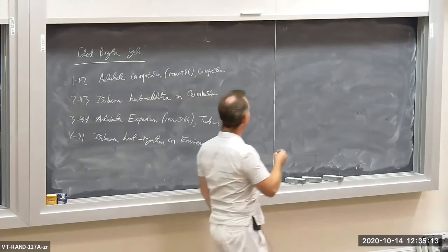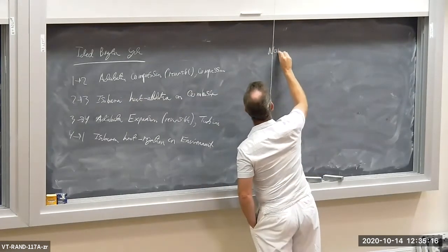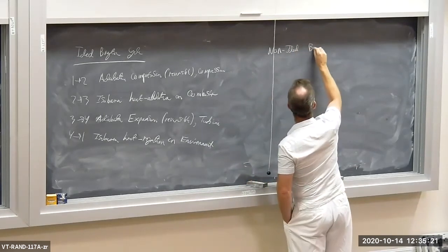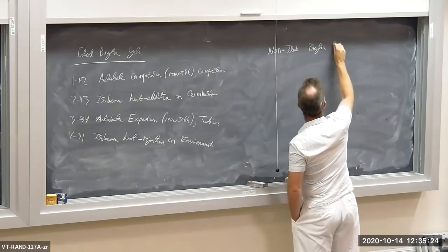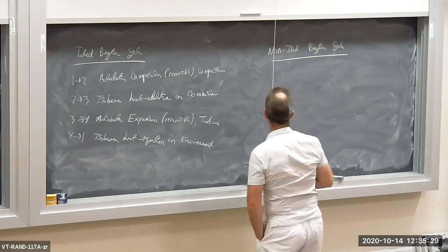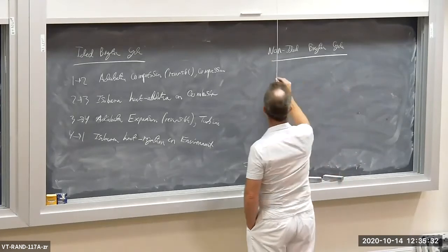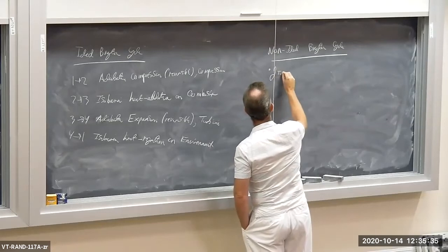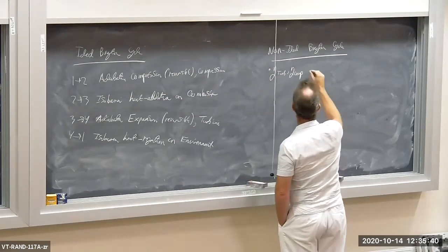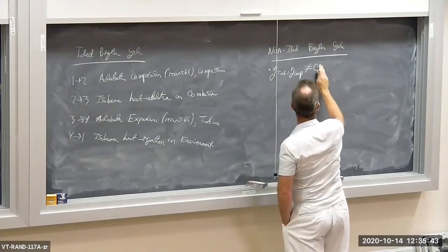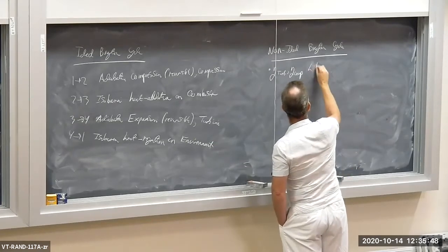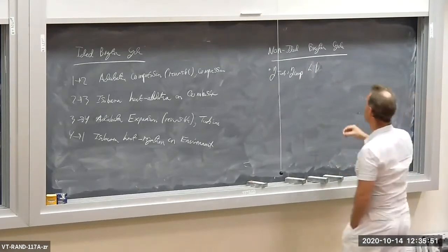So for the non-ideal Brayton cycle, we have efficiency for the turbine and the compressor. So eta turbine and eta compressor, these are isentropic efficiencies. These might be not equal to 1, or I guess I'll just say they could be less than 1. So in other words, irreversible.